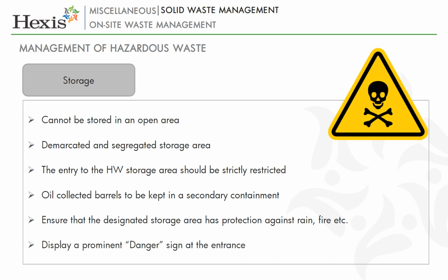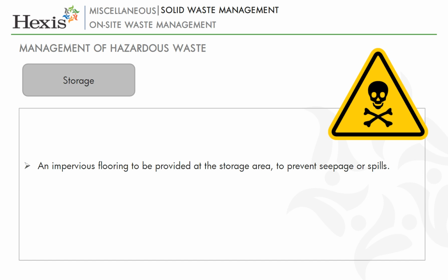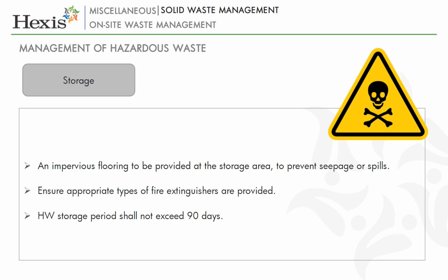A prominent signage should be displayed at the entrance of the storage area along with a danger sign. An impervious flooring should be provided at the storage area to prevent seepage or spills. Ensure appropriate types of fire extinguishers are provided. HW storage period shall not exceed 90 days. Maintain the record of sale, transfer, storage, recycling and reprocessing.